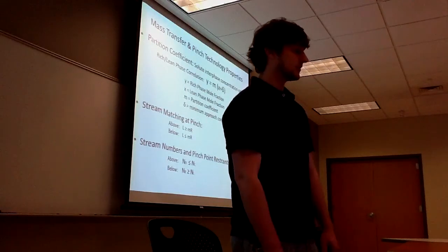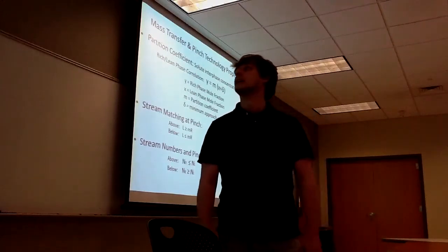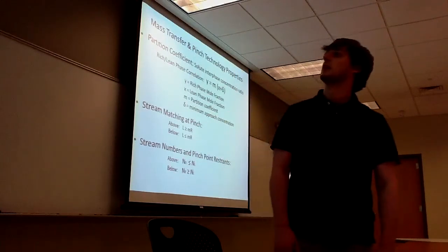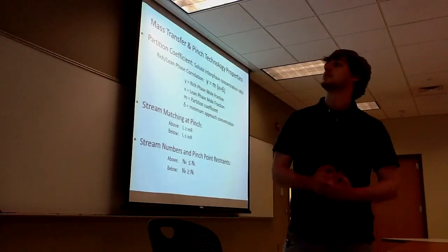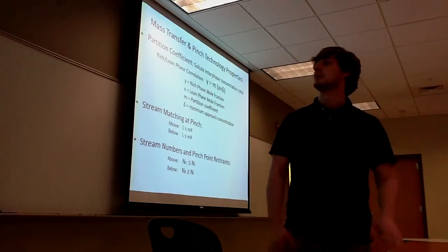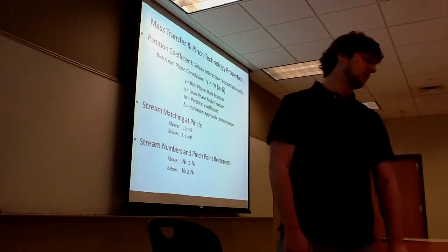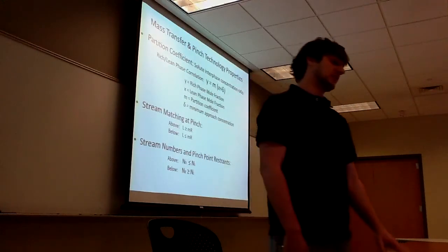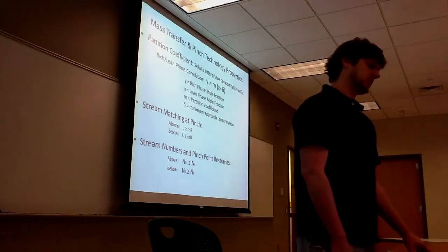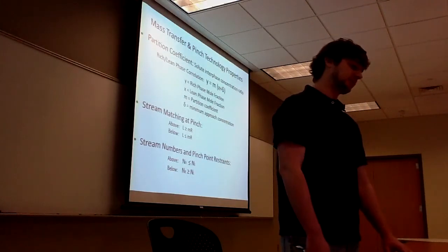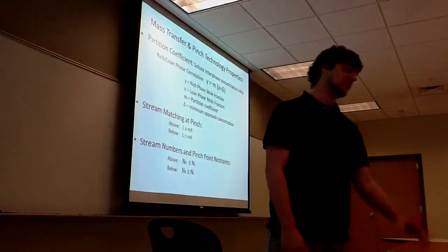Okay, so to go over, there are some very key differences between heat exchanger pinch technology and mass transfer. First being the physical phenomena. First and foremost is the partition coefficient. This one is basically the solute interface concentration ratio for the rich and lean phase correlation. In this equation, Y is the rich phase mole fraction, and X is the lean phase mole fraction, and M is that important partition coefficient that basically defines the stream. And then delta there is your minimum approach concentration, which is the one you're going to specify to be the minimum pinch point.